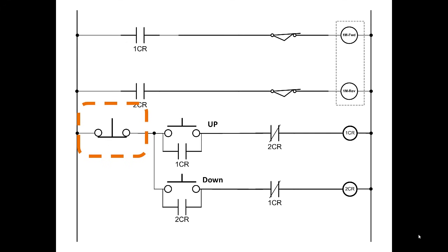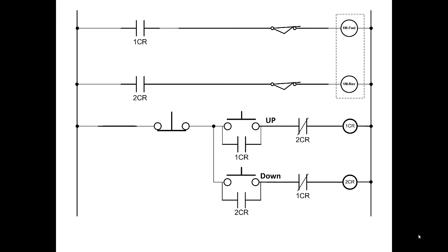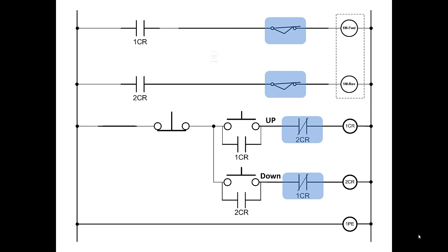There still remains a few more weaknesses in this design. We're going to leave it until later to actually discuss the changes. Now remember that we also mentioned a safety photo eye to stop the door if something is blocked. And before we put that safety photo eye in there, let's review one more time. These contacts are interlocking with the two relays to prevent you from turning both directions on at the same time. These two limit switches prevent over travel.